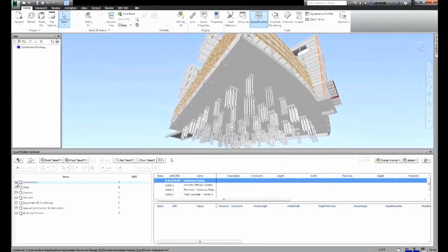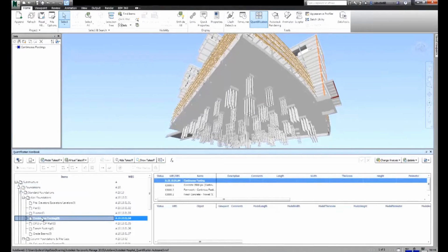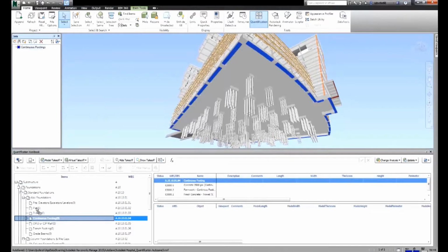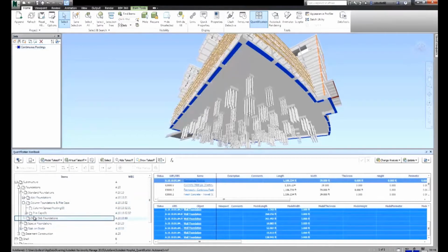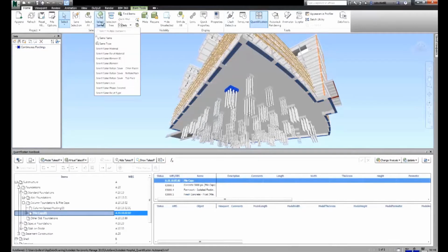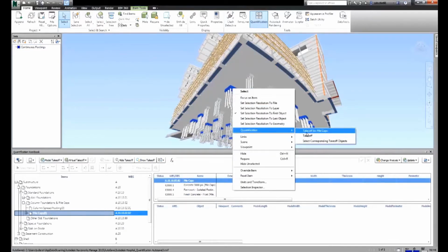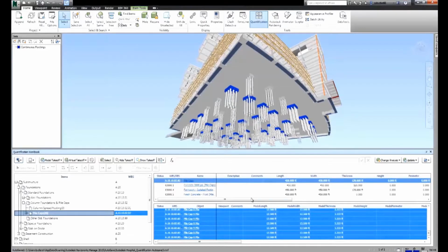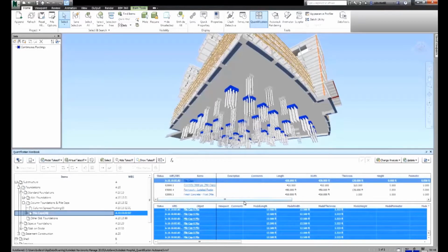Here we're seeing an item and resource catalog used to classify model elements further than the model ordering tools can. When the catalog is available, it is possible to quantify the model using intuitive tools in Navisworks. Simply select an appropriate item within the catalog for quantification, then drag and drop the elements from the model to the appropriate items. The workbook also leverages the item breakdown structures and the resource breakdown structures, and in that we can see a roll-up of the total quantities of an item collection with its resources.